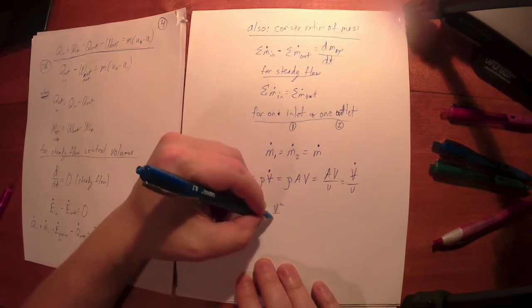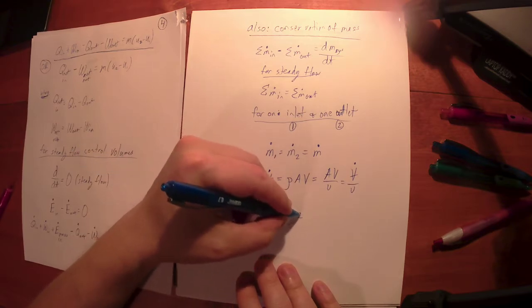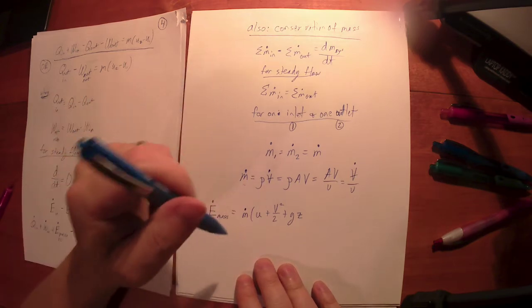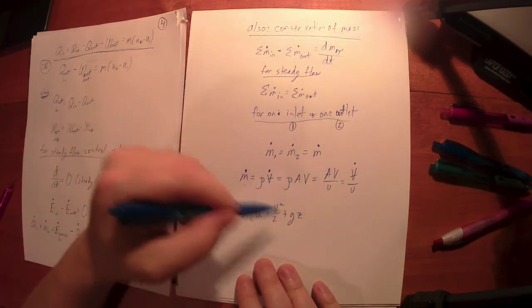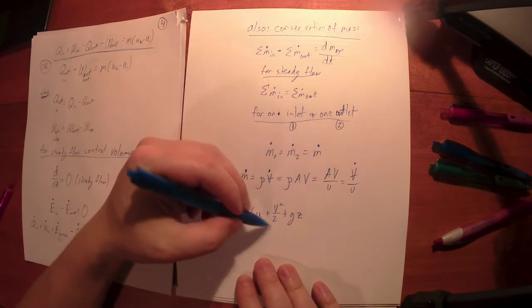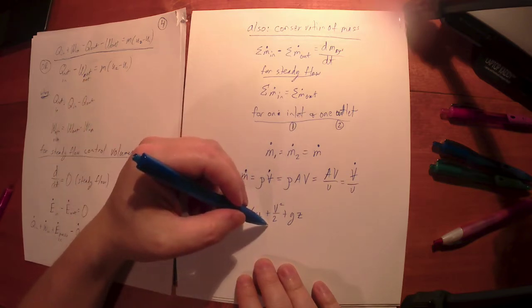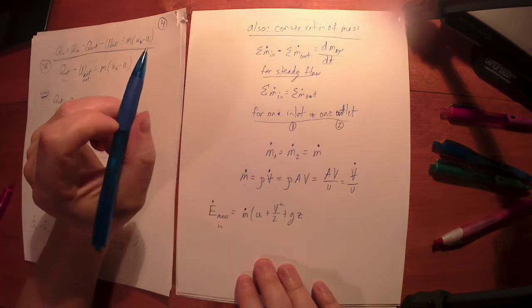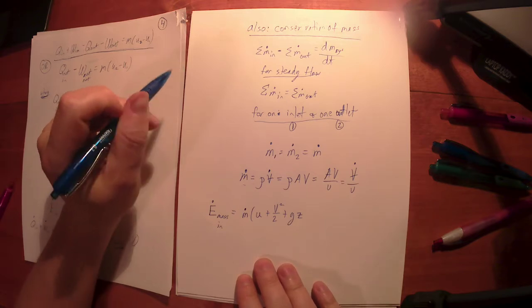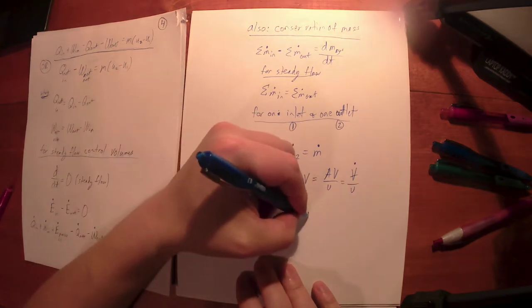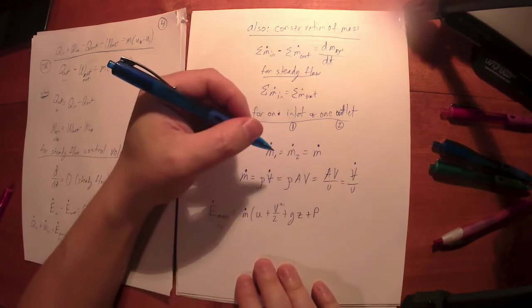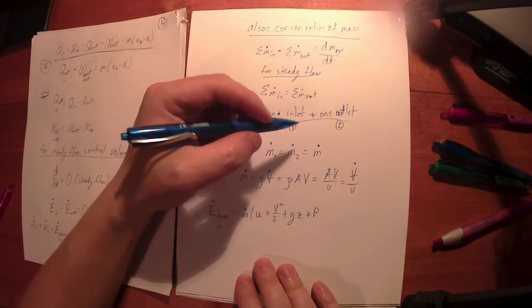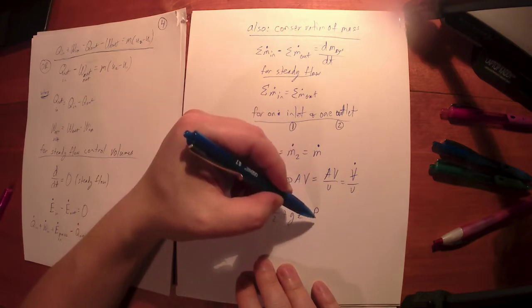It's going to have its own kinetic energy. And it's probably going to have a negligible amount, but it's still there, potential energy. And we've talked about this in class before. If it's stationary, if the mass is not moving, these are the energies that it has. But since it's moving, something causes it to move. It doesn't just move spontaneously. Something pushes it. Something forces it to move. And what causes it to move is the pressure of the mass upstream pushing the mass downstream out of its way. Pressure by itself is not an energy term.